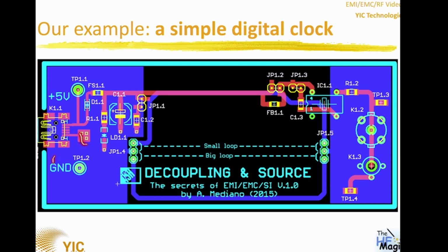So remember, this is a 5 volts line powering my device, and return GND trace is in the lower part of the drawing. The output of the system is a clock signal that I am not interested in analyzing, but we will see what happened in this signal in the scope. So the first thing to do is to power the circuit and to see how is the clock signal and how is the VCC that is powering the device. Clock signal will go to channel number 1, VCC will go to channel number 2.